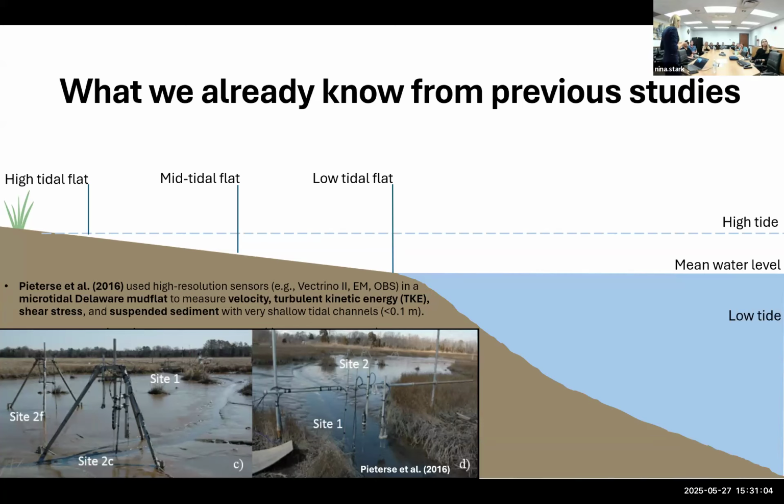The problem is that in the tidal flat the flow is moving so slowly that the boundary layer is much bigger than in the swash zone, so in general you need sensors at different heights above the bed to resolve the boundary layer.